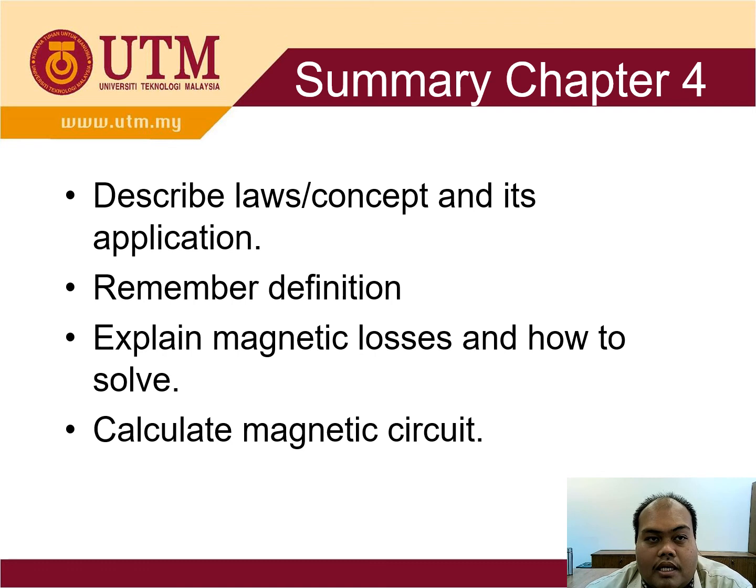And then lastly, to calculate the magnetic circuit. It can be direct to the point, where you have to calculate the reluctance, or given the flux, you have to find the current.